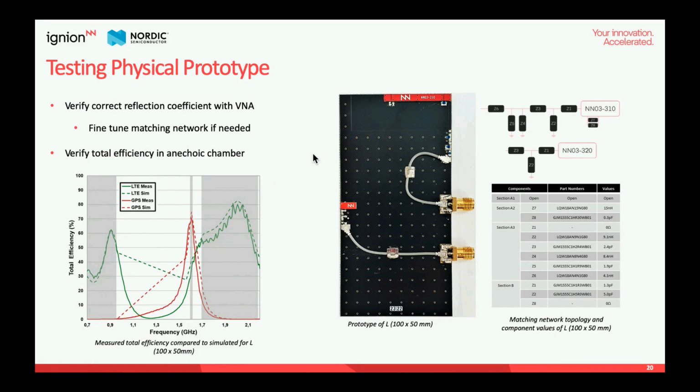Here on the top right we have the Trio chip antenna component, which works for cellular IoT, the green line on the plot on the left. You can see that the green dashed line and the continuous line, which are the simulation and the measurement, are in very, very good agreement. And the red one is for GPS at 1.57, and belongs to the tiny component that you can see on the left of the PCB. This is the Duo antenna booster that, besides being very small, does not require clearance area beyond the antenna footprint.